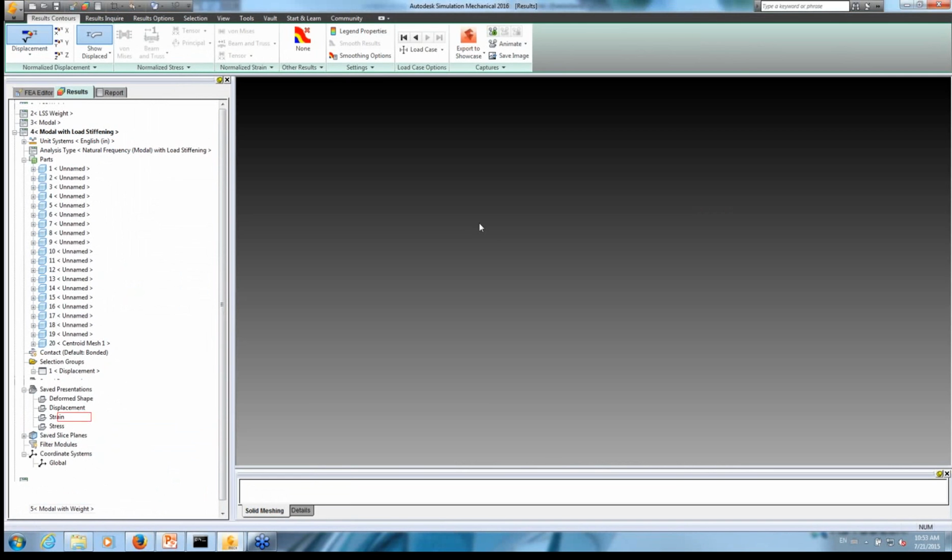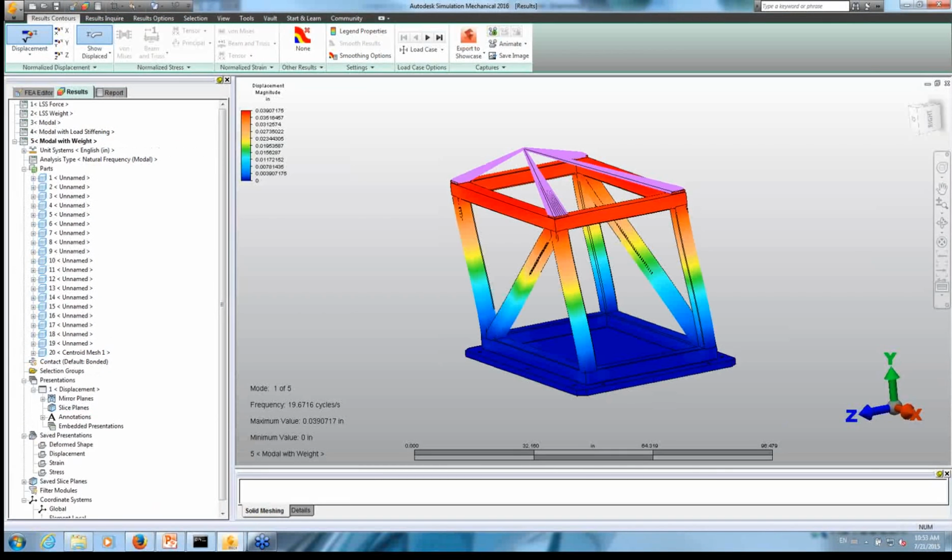So, just to point out this little effect, in this particular version we have the mass attributed to that location, but we don't have a force and we aren't looking at load stiffening. It's throwing out all the load stiffening effects, right? It's looking only at how much the mode shapes change when we add a mass of that much at that location. That's true.